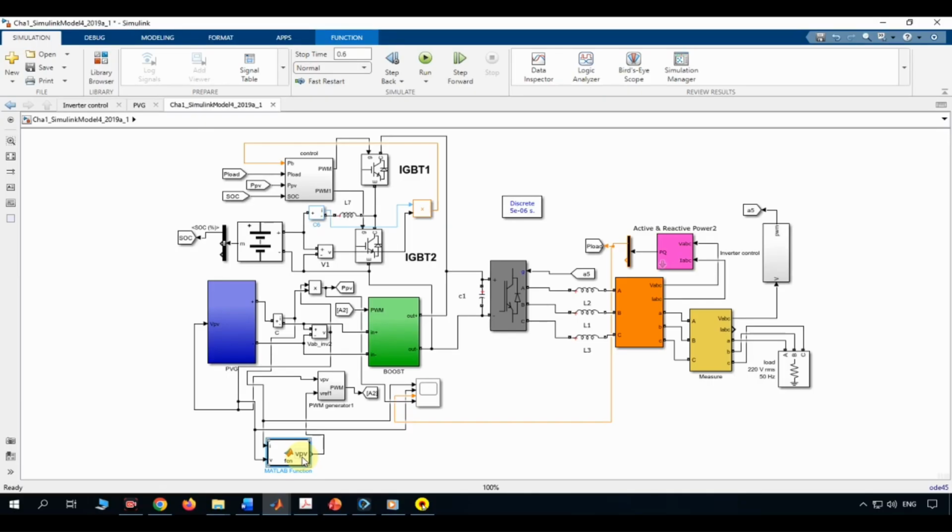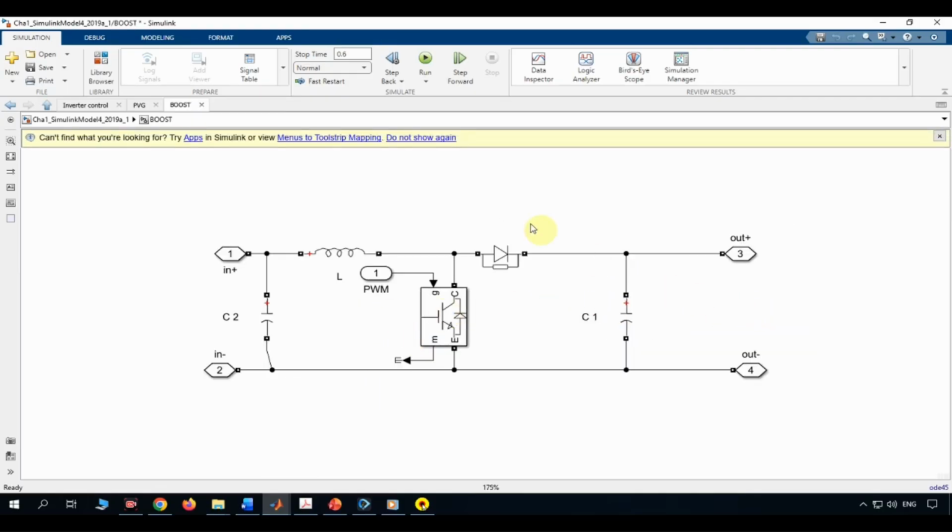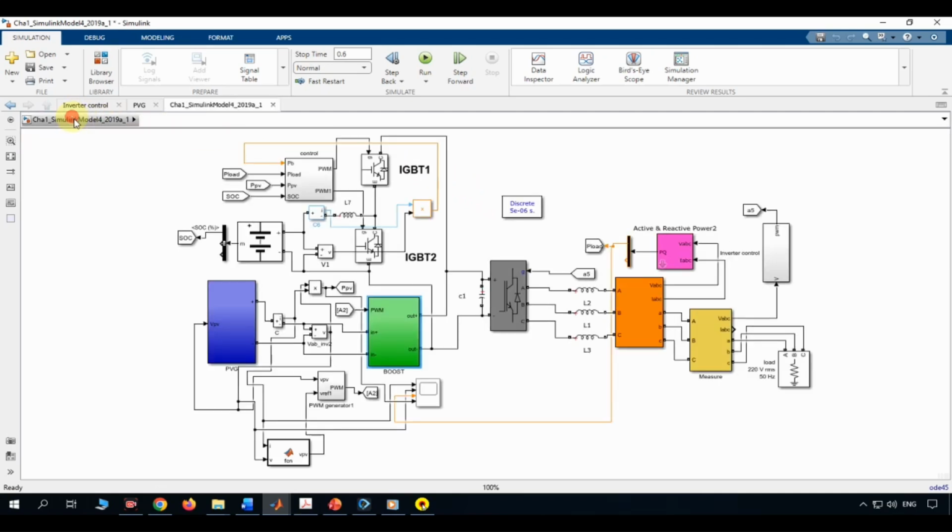That target voltage gets enforced by the boost converter, a switching circuit that physically forces the panel to operate at exactly the voltage the MPPT wants, while stepping that voltage up to a higher DC bus level the rest of the system can use. Now, here's where it gets interesting.